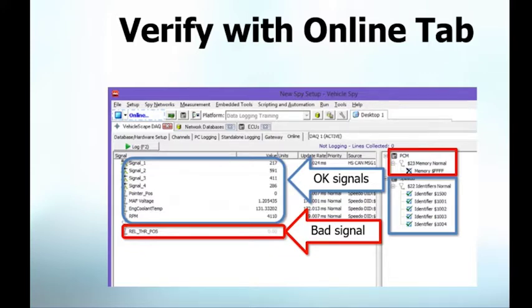It's a very common mistake with a lot of customers where maybe you used an outdated A2L file. So before sending out a logger with the wrong A2L file, which means you're going to get no data, you can quickly verify it with this. So right from the screen, you can see what's updating, and then down here I have one that's not updating. So obviously, whatever ODX file I used wasn't the right one. I'm not returning any value at all.